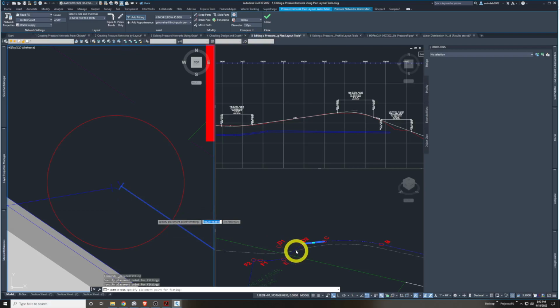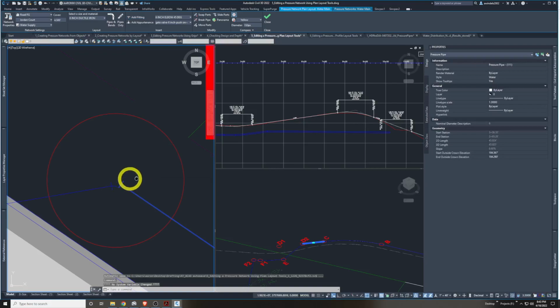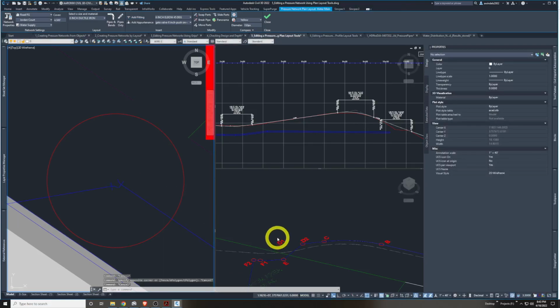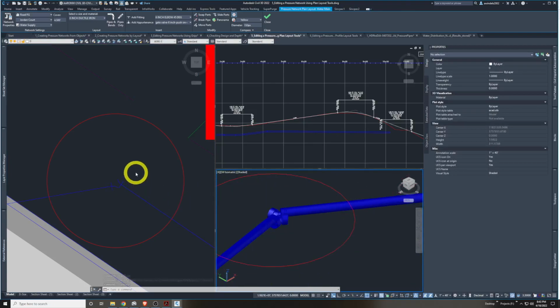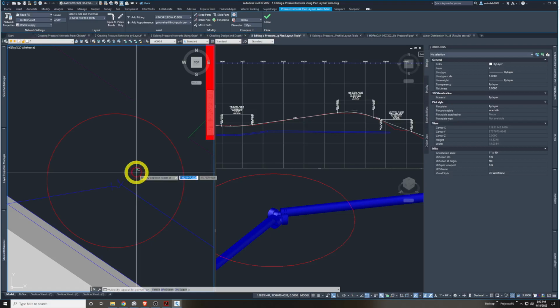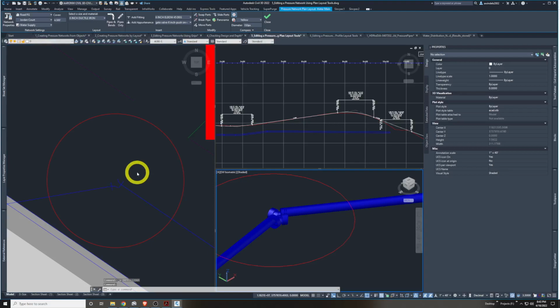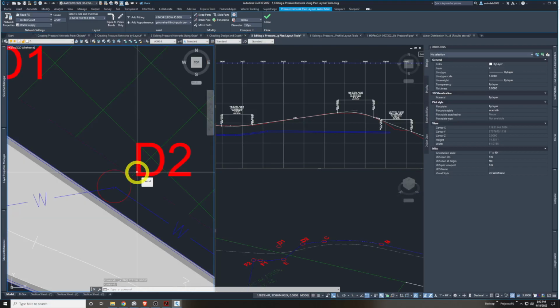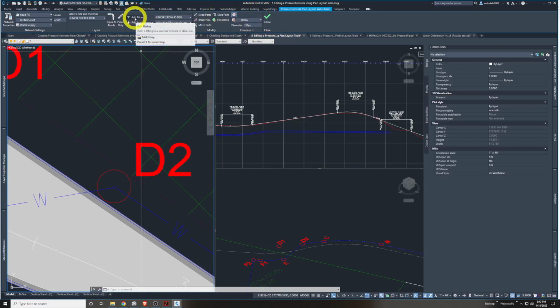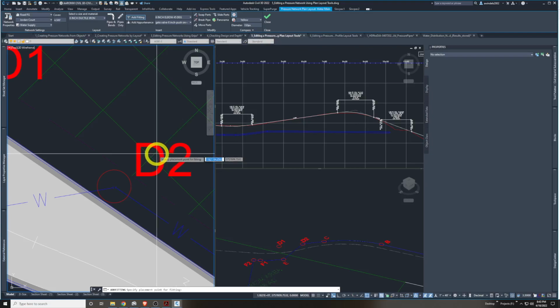So I put 2 fittings in there, which wasn't ideal. Hit escape twice. So I essentially put 2 fittings. Hit Control Z, or undo that. Give this another go. We have all of my stuff staying up here in the ribbon. Add that fitting again.